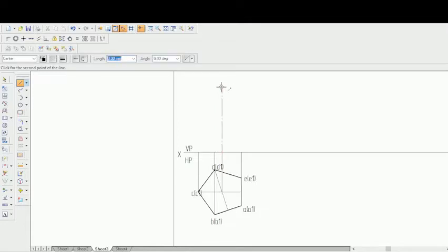Enter. Let it be 90 degrees. Now let's use the visible line and draw the remaining portion of this problem. Using this alignment indicator, you will get it correctly. And let's draw a visible line here also, here as well. So that completes that. That is almost the front face.